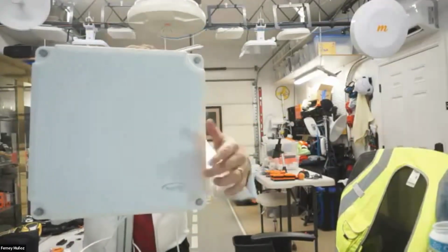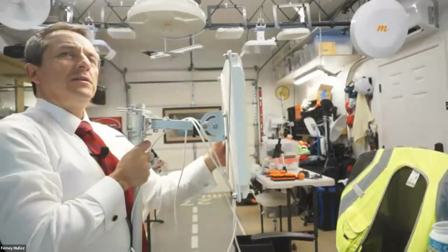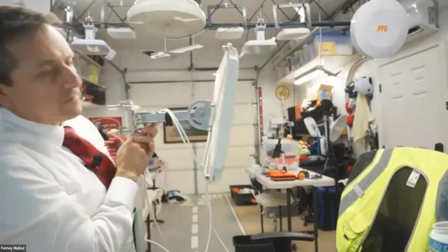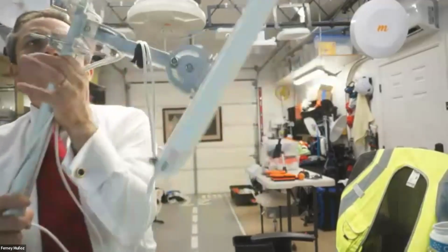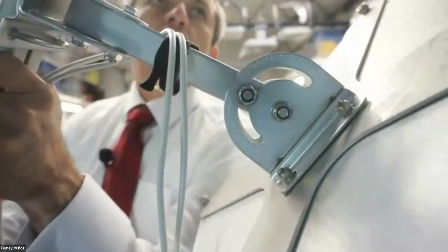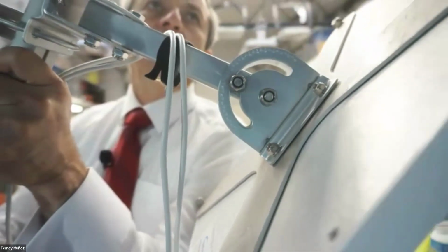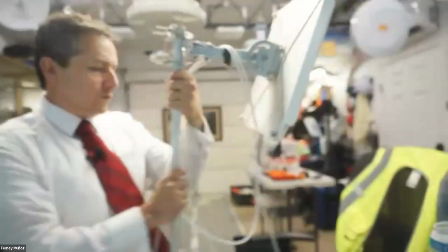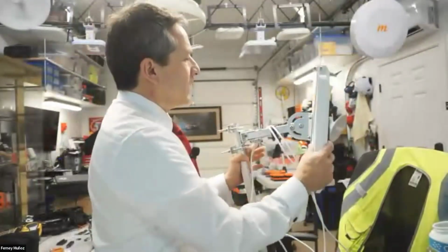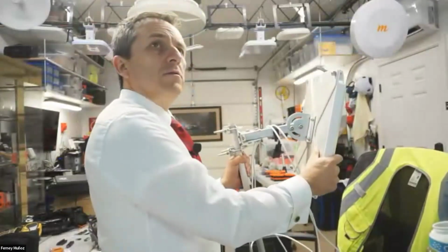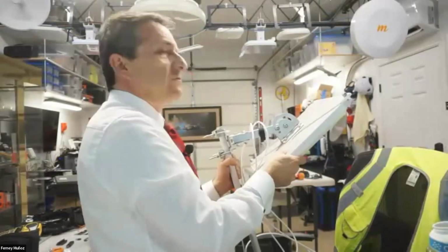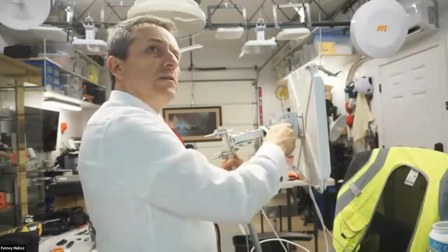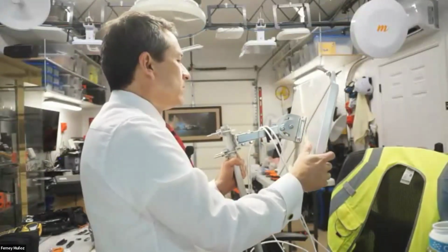The tilt, what's called the tilt, is this, the 10 degrees, 20 degrees. And the antennas like this one, it has some markers in there. You see those, Jocelyn? You see the markers like the number of degrees? Then that's what you would use to see, oh, if I need to have these guys 10 degrees down or 20 degrees down or 30 or 45 degrees down, that's where you move it and then you tighten these screws and adjust it so that it's at that right angle.